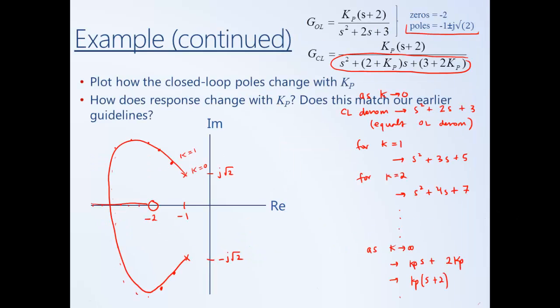Okay. Going back to this example of a root locus that we drew previously and recalling this relationship that we just derived, every value of S which is a closed loop pole, or a possible closed loop pole for our system, must satisfy this equation.